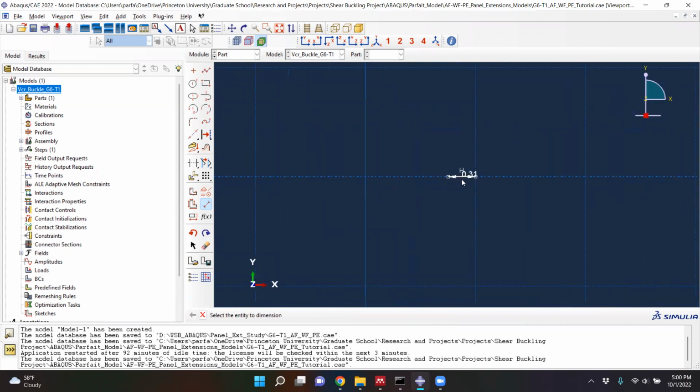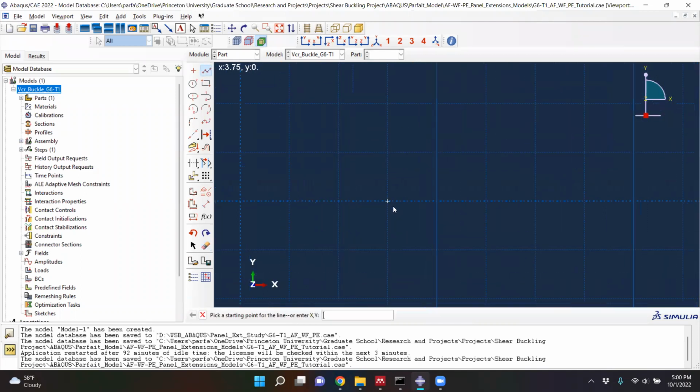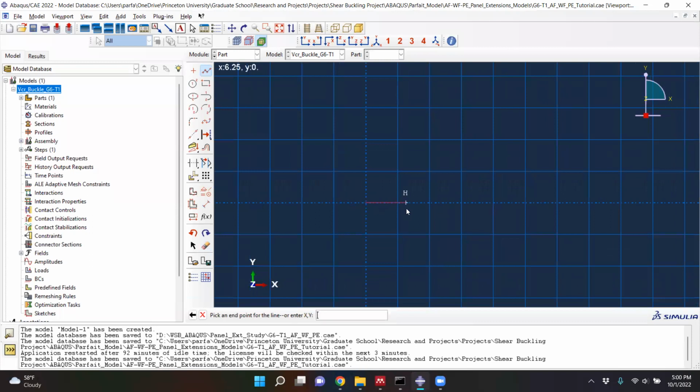And so now we have a horizontal line here. I'm going to erase this and redo this process. So delete, done. And so let's do it all over again. Create lines. I'm going to draw a horizontal line. And then I'm going to select the dimension, click, and then rename this dimension to 0.308, enter.